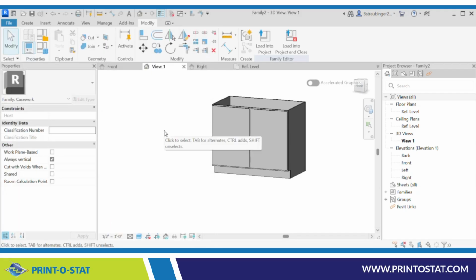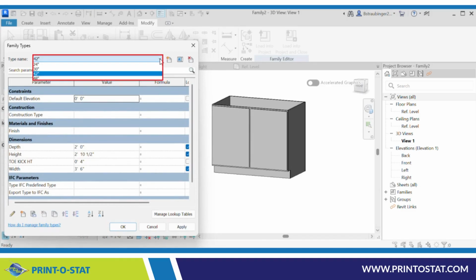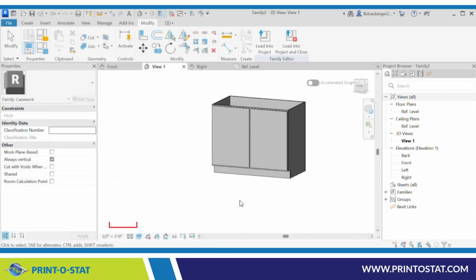Now, let me go back to there. I want to show you this. Type. When I bring this into a project, these are the types that are going to show up in my project. These types are based on the width. Your types can be based on any parameter you would like them to be. Could be color, could be material, could be anything you want. And you can name it that way. So I'm going to select OK.